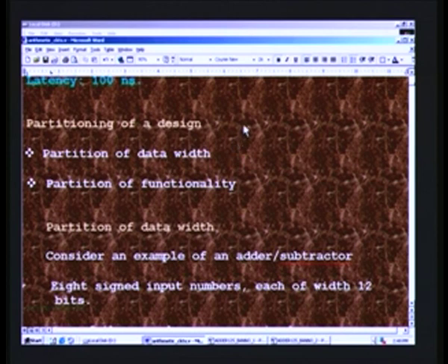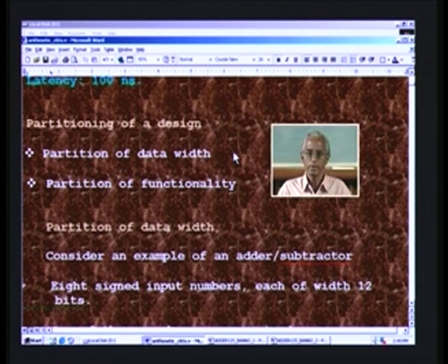Say for example, we have an adder or any other data processing which processes, let us say, 16 bits, and you can add two 16-bit numbers, and if you do that, it will be time consuming, as we will see a little later. A better way of doing it is to bifurcate that 16 bits into two 8 bits and then add only 8 bits at a time. That will be faster than adding 16 bits, but you can pipeline here. You can start adding the LSB first, and then in the second clock, in the second register, that is process 2, you can add the MSB.